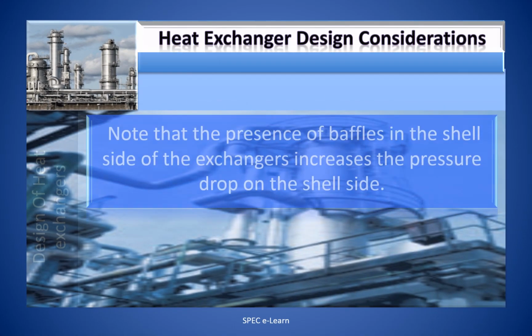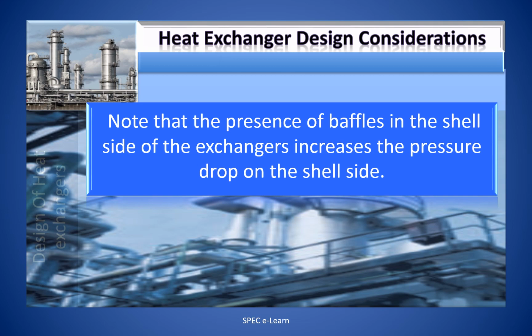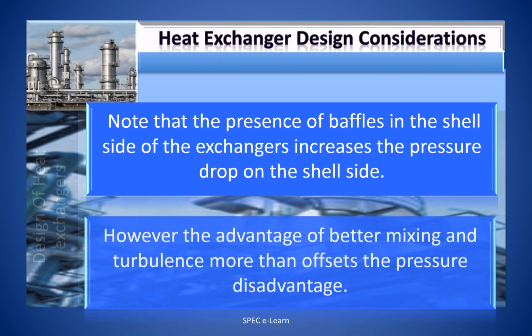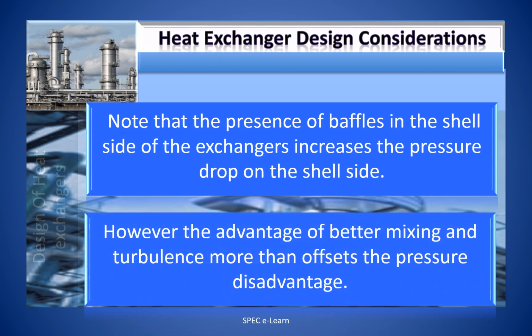Note that the presence of baffles in the shell side of the heat exchanger increases the pressure drop on the shell side because of the restriction area. However, the advantage of better mixing and turbulence more than offsets the pressure drop.